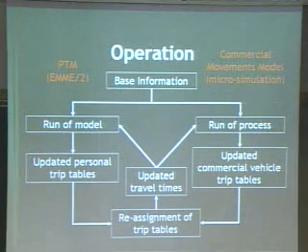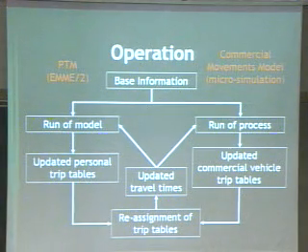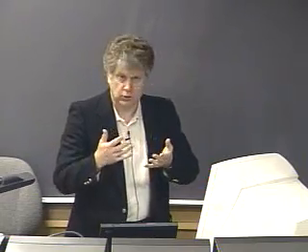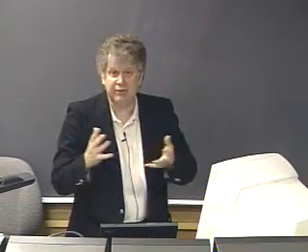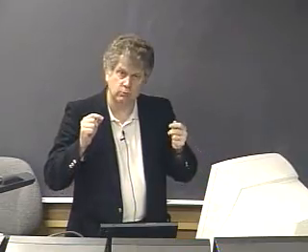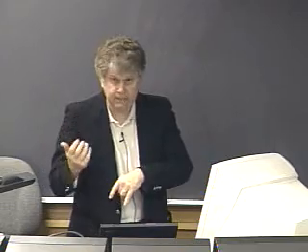Maybe one more thing to say on this. The microsimulation has a random component to it. So like I said, we know we're not going to get it right for actually every individual vehicle, but when we add things together, we're comfortable about what we get overall. But still, when we run it one time, then we run it again, then we run it again, we can get slightly different answers overall. So the process we have to go through there is we have to run it a number of times and then take the average values that we're after.